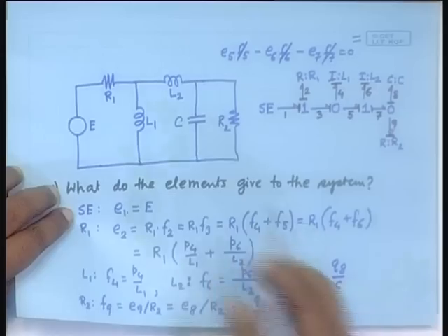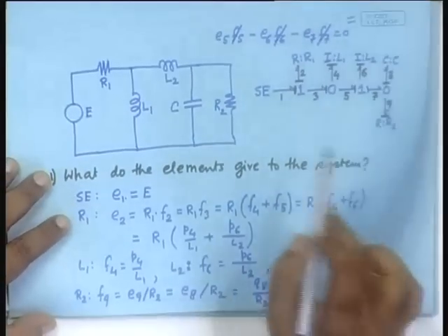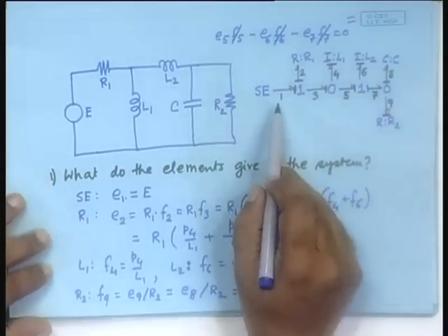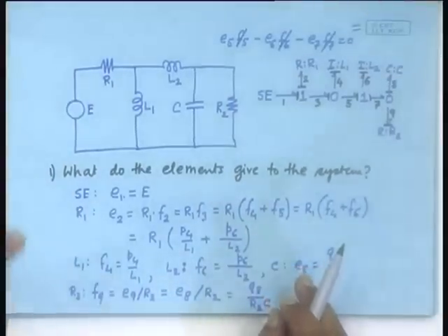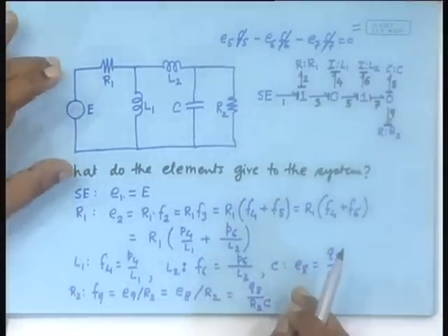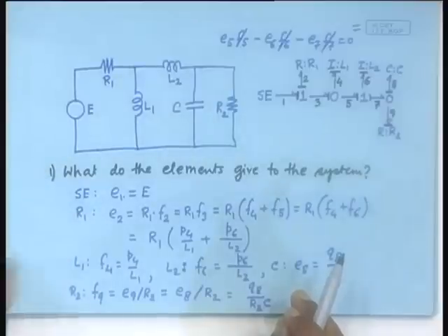The blind procedure is something like this. Say we take this circuit, for which we had obtained this bond graph by simply working by logic. Now, the procedure, which is somewhat algorithmic, is to identify the points that can be at different voltages, what are called the nodes. So, what are the nodes here?